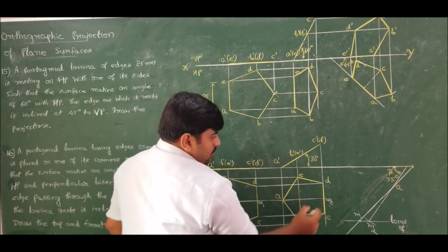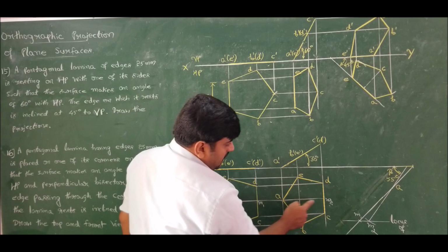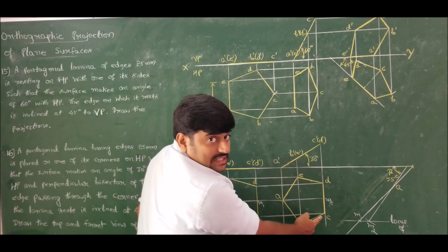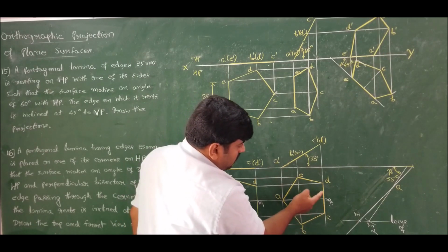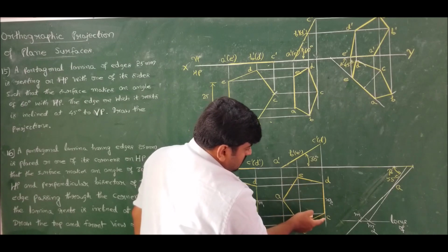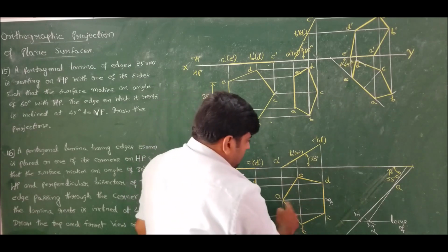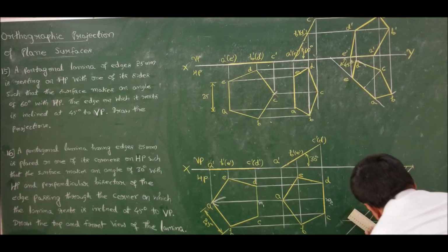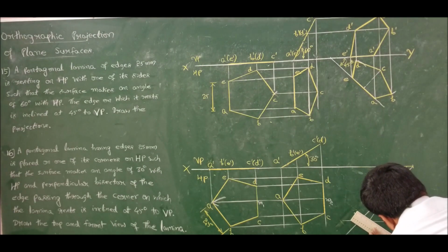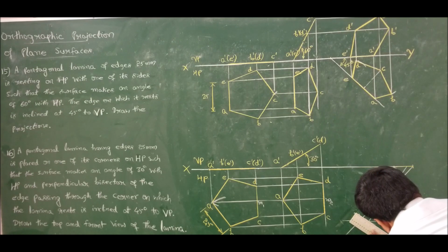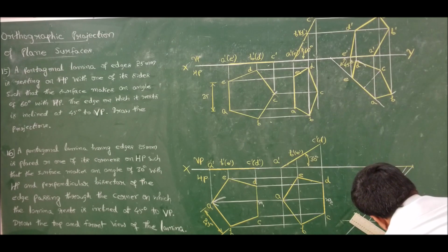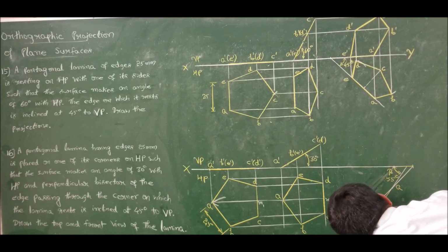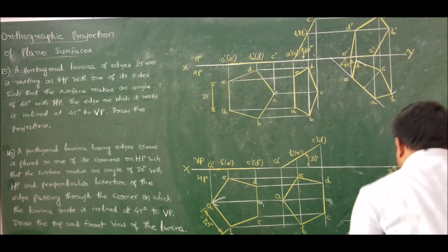So now I got AM2. Careful observation reveals that AM2 is a perpendicular bisector for DC. Correct? So therefore DM2 is 12.5, CM2 is 12.5 and AM2 is a perpendicular bisector for DC. So therefore draw a perpendicular line having a measurement of 12.5 on either side of M2.